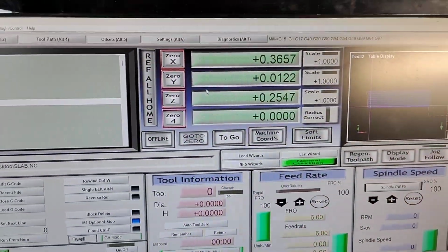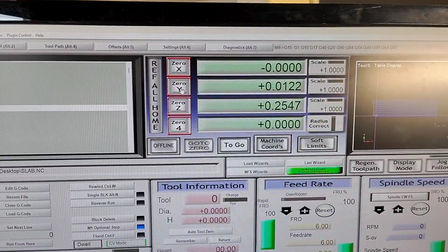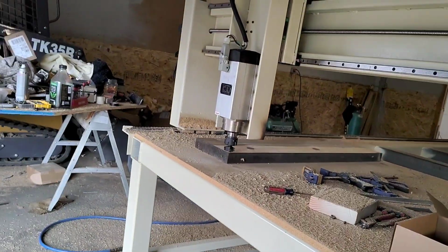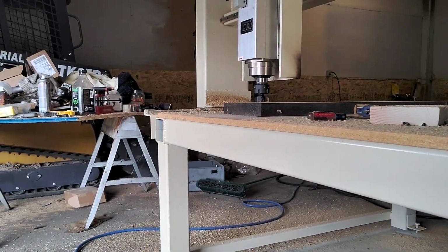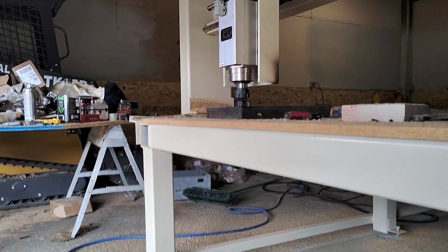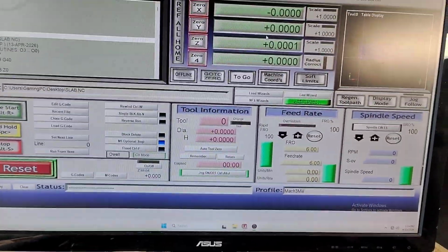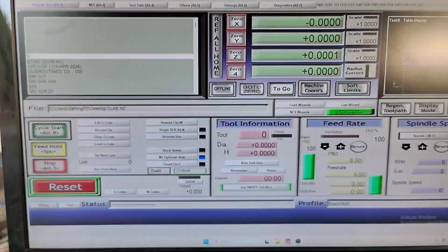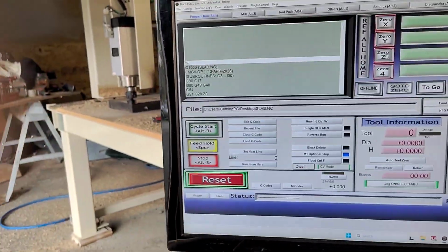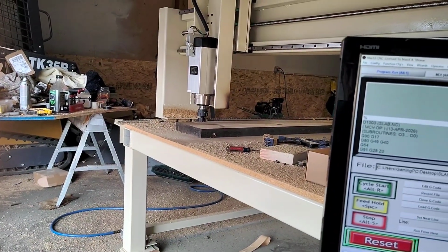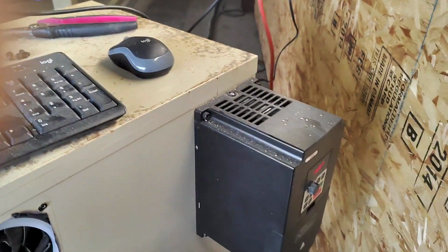For the X and Y position, we'd 0 X and we'd 0 Y. And then, I'll just get the... And that's roughly 0 Z. Oh, I was really close, a 10,000th of an inch, not bad. So at that, let's 0 the Z too. And at that point, I like to move my tool up out of the way with the keyboard and start the spindle, which will be in the following video, and off we go.